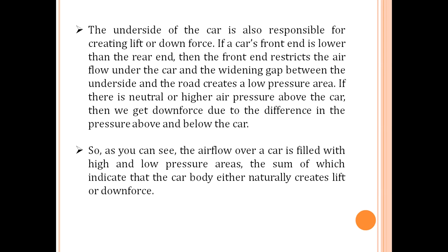When the air enters under the vehicle, the air molecules find the widening gap between the underside and the road, and as a result the air molecules are accelerated. The speed or velocity of these air molecules will be increased. So when the velocity of the air molecules is increased, a low pressure area will be created.